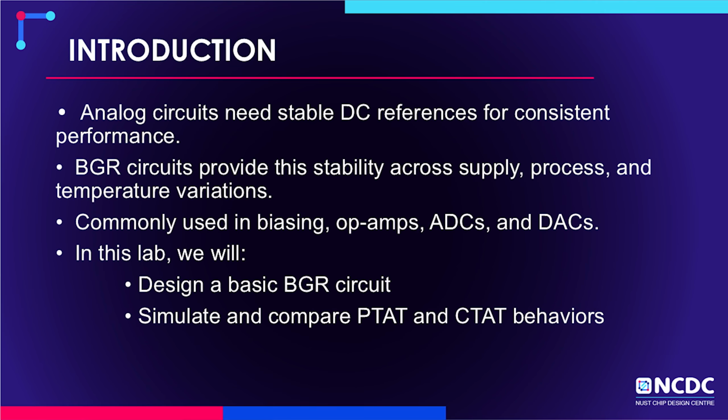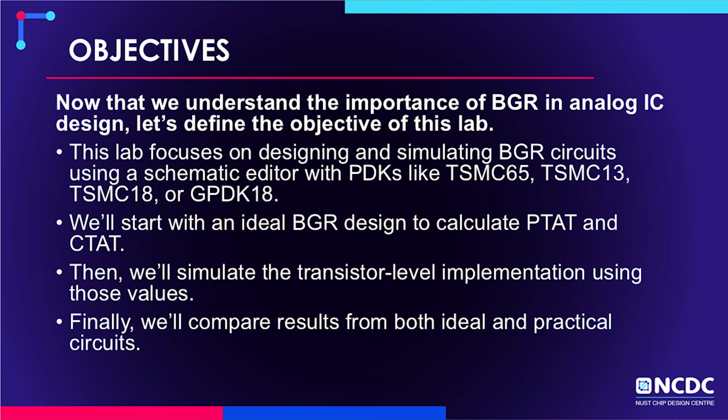Analog circuits need stable DC references for consistent performance. BGR circuits provide this stability across supply, process, and temperature variations. Commonly used in biasing, op-amps, ADCs, and DACs. In this lab, we will design a basic BGR circuit and simulate and compare PTAT and CTAT behaviors. Now that we understand the importance of BGR and analog IC design, let's define the objective of this lab.